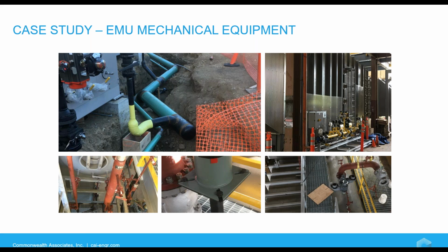For CHP plants supplying steam, protecting the piping and, in conjunction, the people around the equipment from the pressure and temperature of steam can be a life or death situation. Proper sizing and installation of relief valves to protect from overpressurization often falls to the HRSG or boiler supplier, but every engineer should do their due diligence when reviewing to ensure proper sizing.